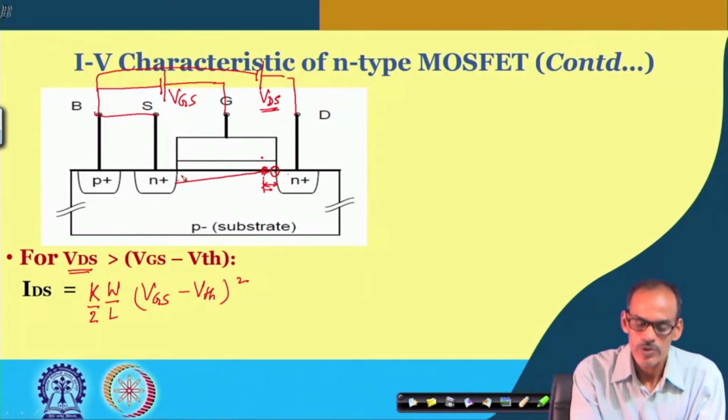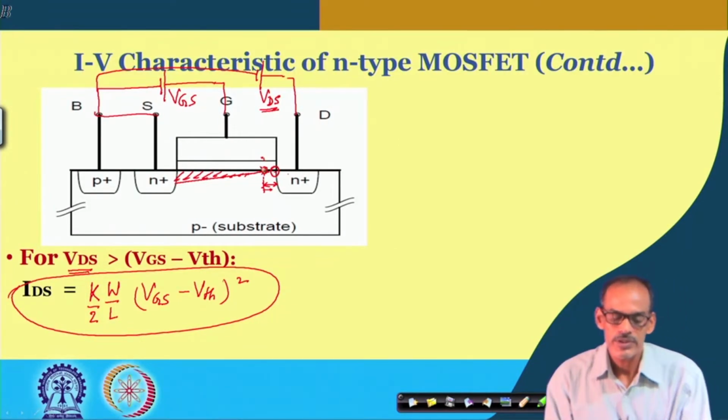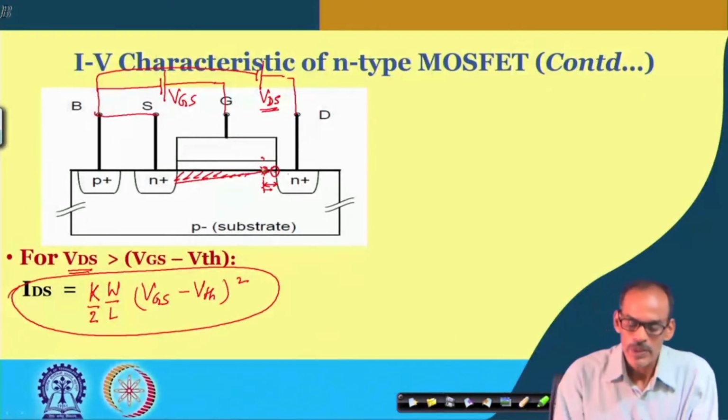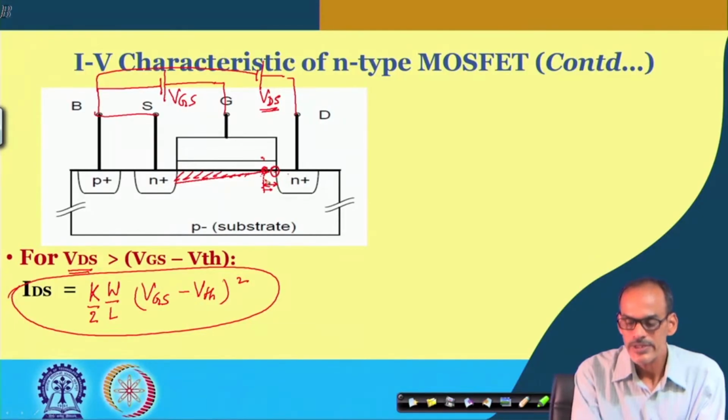As a result there will be a very strong field. So, you may say that this portion of the device is working the same as the device we have discussed here, where at this edge the conductivity is approaching 0, and whatever injection of carriers is happening, those carriers are basically jumping across this junction from the pinch off point till the edge of the drain.